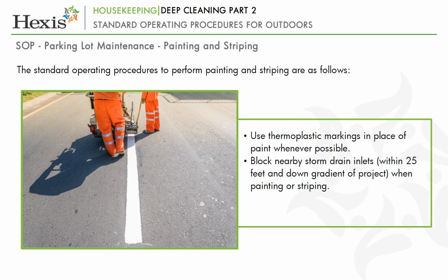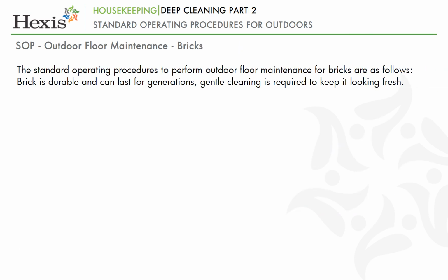Block nearby storm drain inlets within 25 feet and down gradient of project when painting or stripping. Promptly clean up any spills of paints, cleaners or other chemicals. The standard operating procedures to perform outdoor floor maintenance for bricks are as follows.